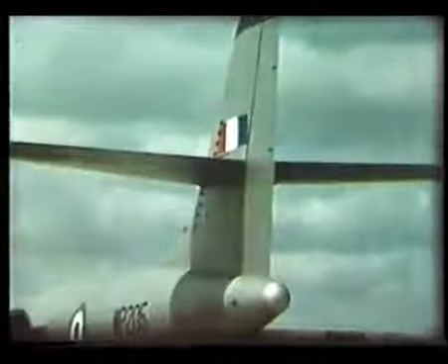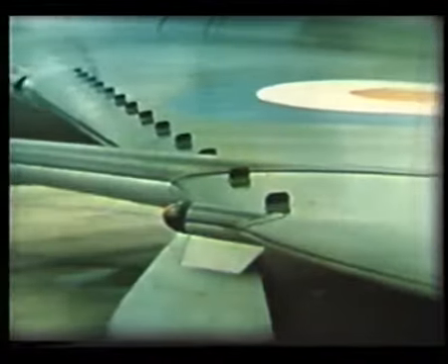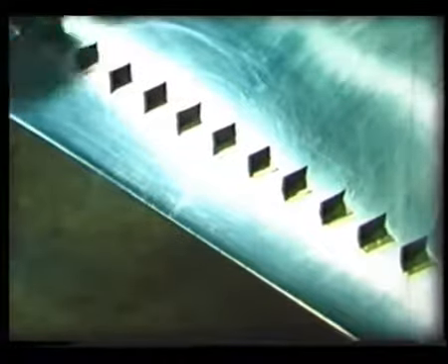Flow separation can also be made less severe by fitting vortex generators, rows of small metal vanes, each of which leaves a tiny vortex behind it. These vortices stir live, fast-moving air into the sluggish boundary layer. These two pictures are of the same aerofoil. In the upper one, vortex generators are fitted. They can be seen jutting out in silhouette.